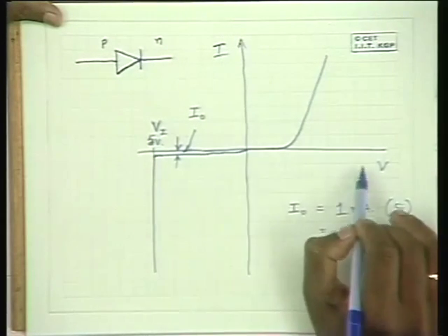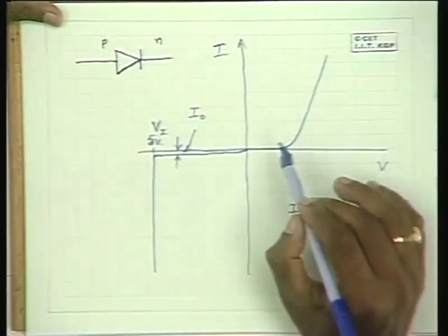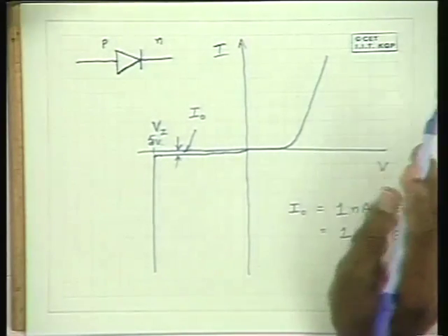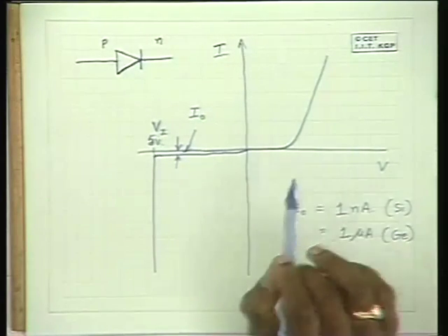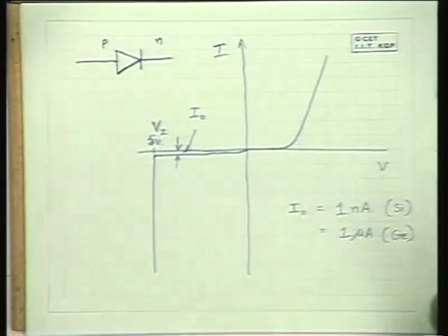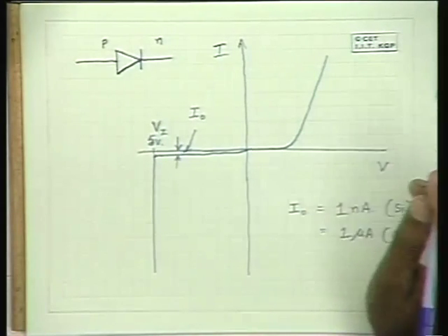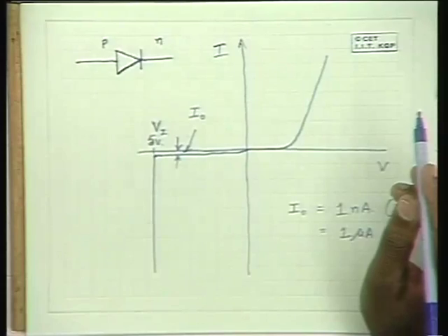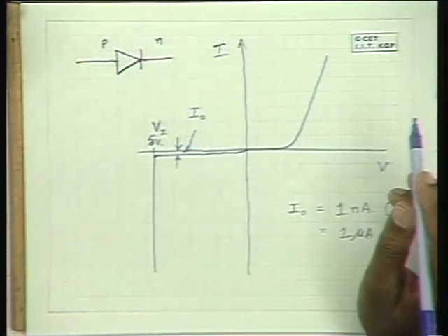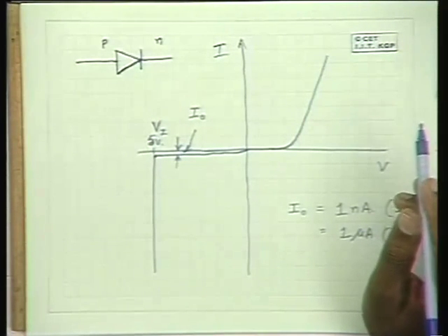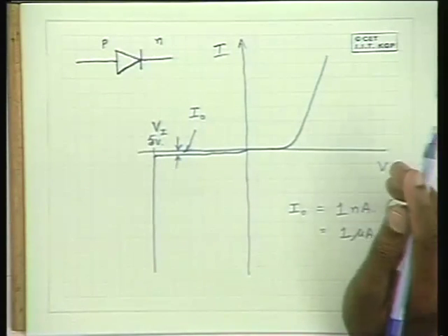The volt ampere characteristics is the characteristics you look for. So this gives the characteristics of the diode. If you apply some positive potential, it allows the current to flow, and if you apply some negative potential across it, it doesn't allow appreciable current to pass through up to a certain voltage, and of course beyond that it allows the current to pass through.